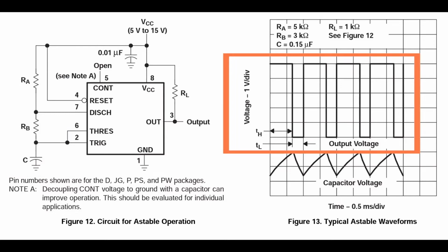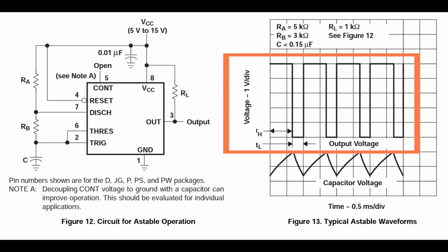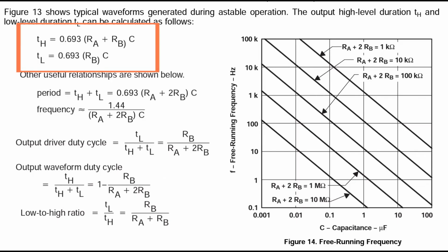And it's a cool thing. It's a kind of an oscillator you produce just by having such a 555 timer. And it's a cheap component, and you can feed it with, for example, like here 5 volts. And you put in 2 resistors and a capacitor, and boom, it swings, and it's cool. So let's see on the next page of the datasheet what kind of waveform we can produce here.